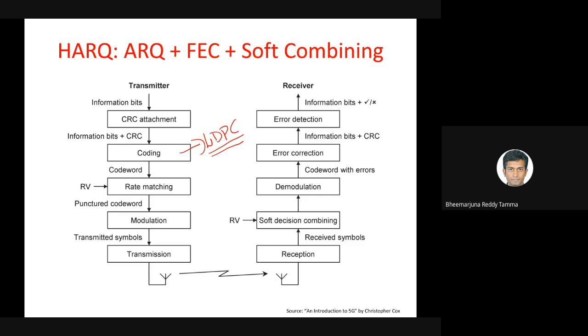The CRC that you use in the MAC layer and here at the CRC attachment are only error detection codes. They check using some CRC polynomial and say yes or no, but they cannot be used to correct bit errors. To further improve the transmission success, we do channel coding. In channel coding, you take the data and add forward error correction. You add lots of redundancy bits, also called parity bits, and then you send it down the stack.